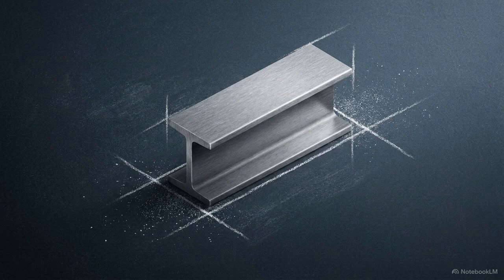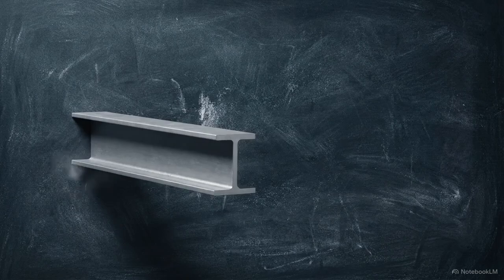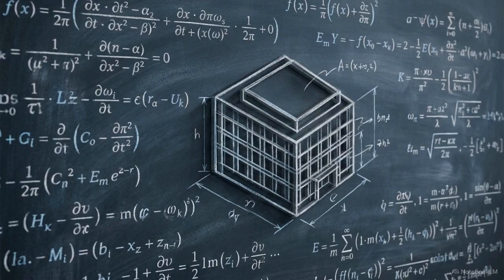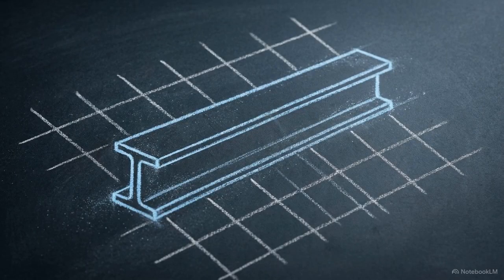Imagine a steel beam suspended in a frictionless, empty void. If a force strikes it dead center, it doesn't bend or absorb the load, it just instantly accelerates and spins out into space. When we assemble a global set of finite element equations for a structure, we haven't actually built a functional model yet. We've just mathematically described that free-floating beam.